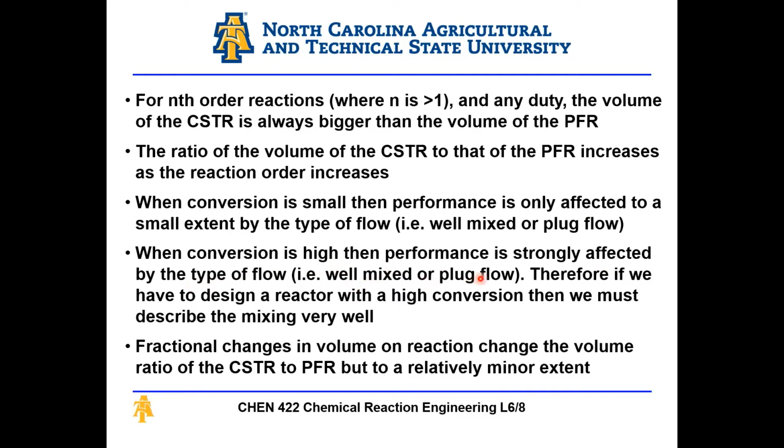well-mixed or plug flow. Therefore, if we have to design a reactor with a high conversion, we must describe the mixing very well. This is an extremely important point when you go to work in industry, to understand that the mixing behavior in the reactor plays a significant role in how it operates. And a lot of the time, reactors underperform because the mixing is not done properly, or it's in a plug flow regime when it should be in a mixed regime, etc.